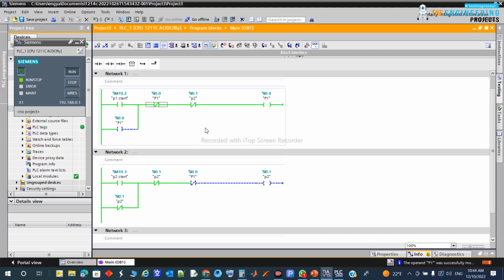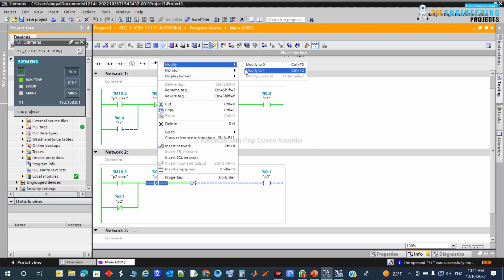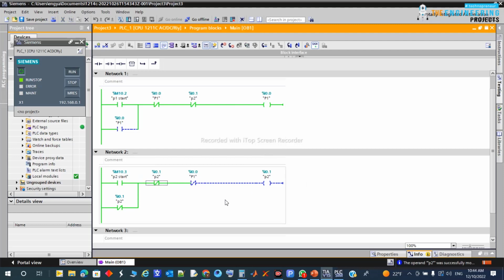If you have such a thing, and you switch this one to on like this, you need a stop button to make this work, because now you have latching, and this one needs to be on. So this is the start button, and this one is not working, and this one is working.